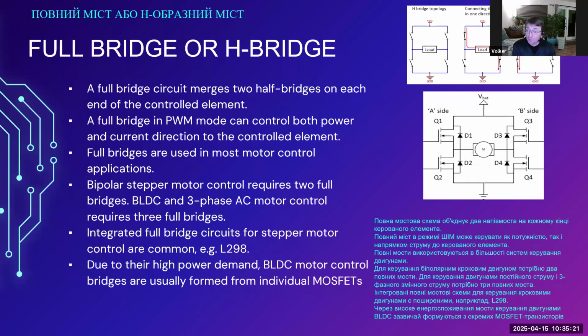If you have an H bridge, you can PWM a motor. If it was a DC brushed motor, not a brushless motor, you can control the speed through PWM and you can reverse the rotation direction. That is a very classic application for an H bridge.